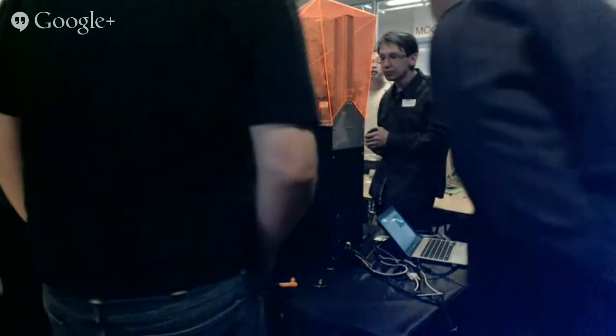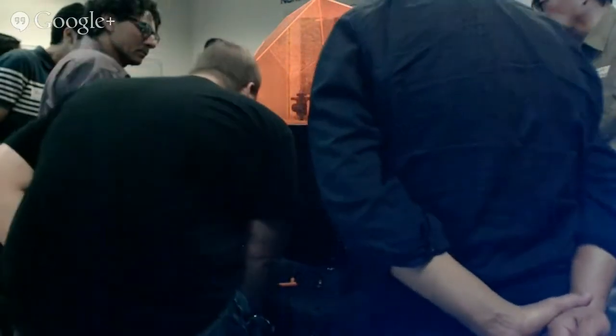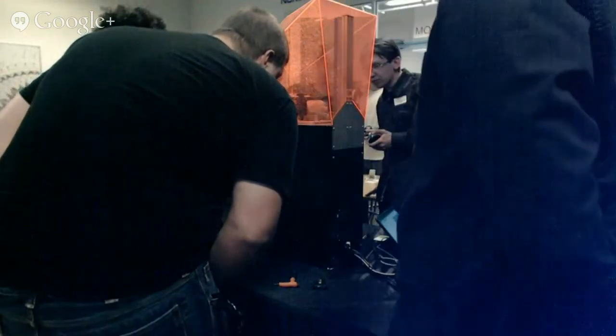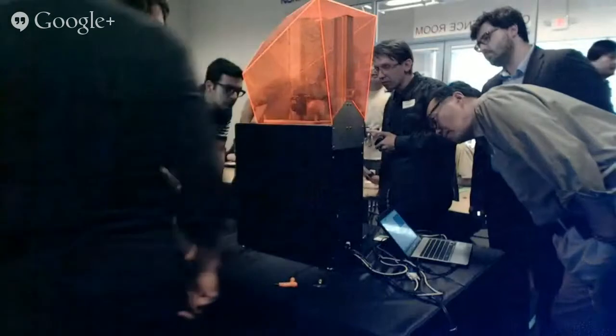Resin is not good for the environment. Yeah. You have to be careful with the disposal. Cured resin is pretty much regular trash. And cured resin is not toxic. It doesn't react with anything. It's not dangerous to fish or wildlife. Cured resin is pretty unreactive stuff. In fact, that's one of the really good things about using resin compared to ABS or PLA: resin is very, very chemical resistant once it's cured. It's also very temperature resistant once it's cured, because it's not a thermoplastic. But liquid resin is a hazard to fish and wildlife.